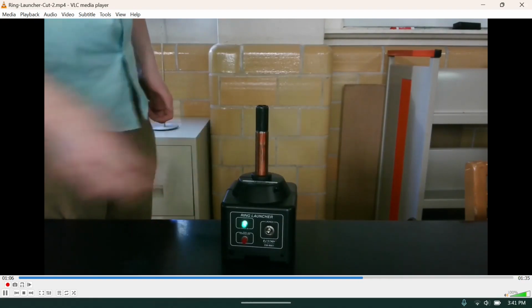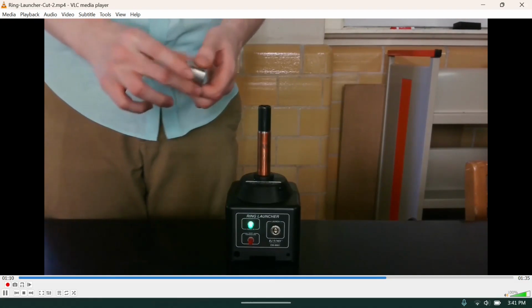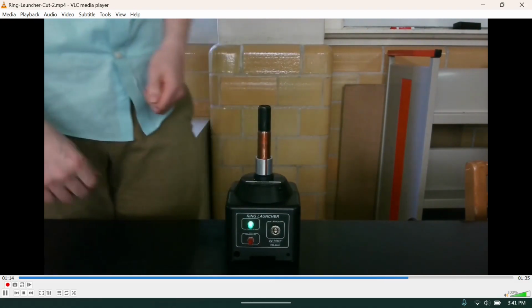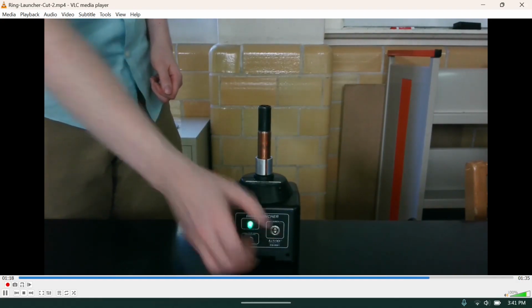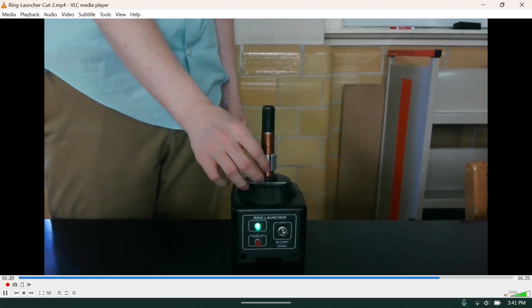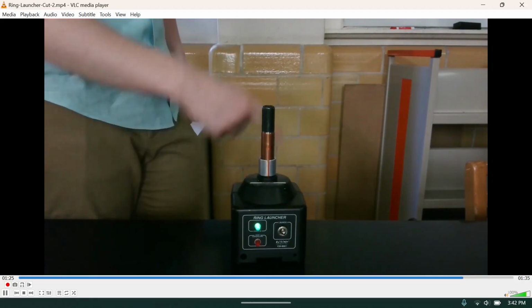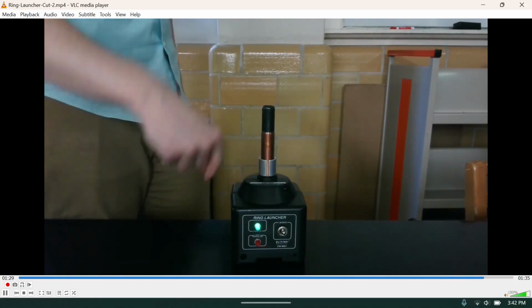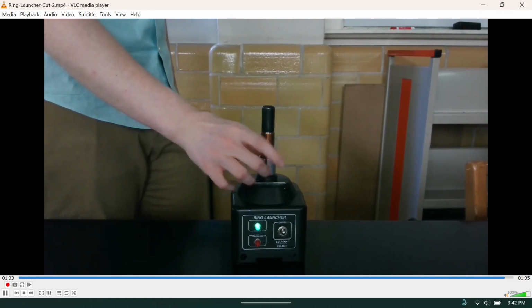What if we had a little cut in the ring so that current can't flow all the way around? What do you think happens when we pulse it? Let's see. Not much of anything. And it's because if we have that cut, current cannot flow all the way around the ring, and so it can't create a magnetic field that opposes that change in flux. So the two don't repel.